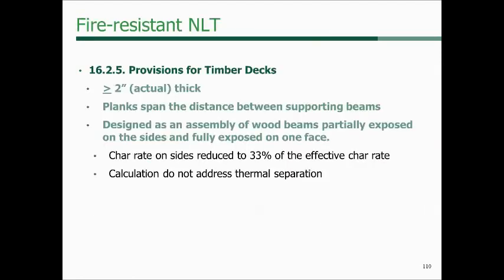Now, where do we find the application for nail-laminated timber? Well, nail-laminated timber is similar to timber decks, which is covered under 16.2.5, and there is an actual minimum thickness requirement of 2 inches or greater. The key is that the planks, the nail-laminated timber members, need to be supported from beam to beam. In other words, you can't cantilever and have a joint mid-span or in between the spans. They have to be supported on each end.